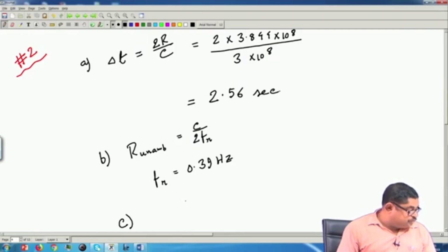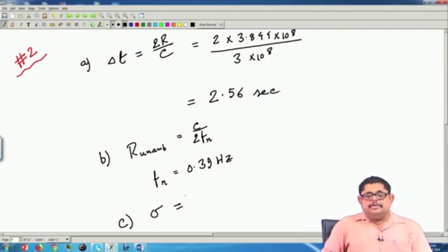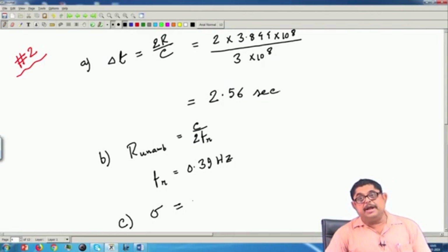Then, the conversion: convert the RCS given in meter square to dBsm. Now, remember what is the definition of RCS, because to convert it to dB, which multiplier should we use, 10 or 20? I think you know that for primary quantities like voltage, current, etc., we use 20 as a multiplier, and for second order quantities like power, energy, etc., we use 10.